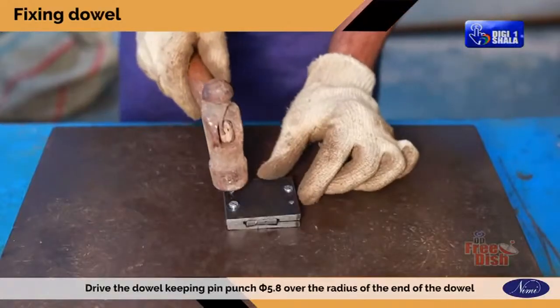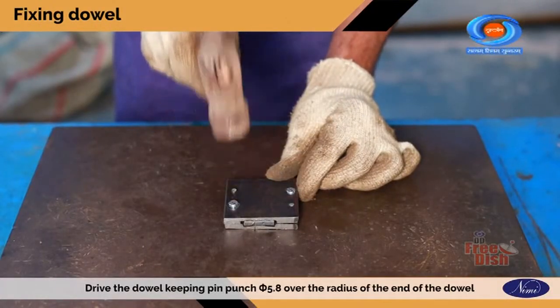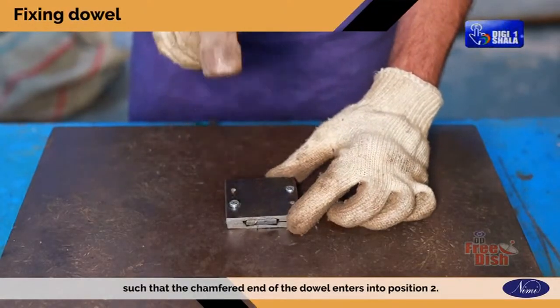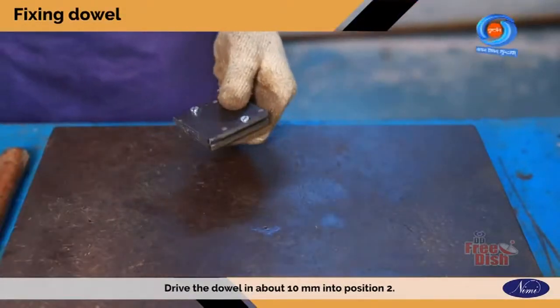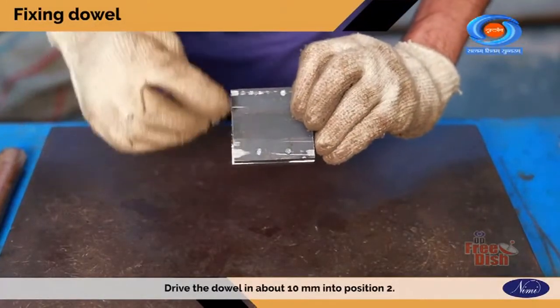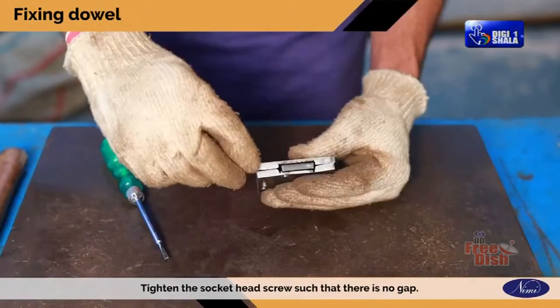Drive the dowel keeping pin punch diameter 5.8 over the radius of the end of the dowel such that the chamfered end of the dowel enters into position 2. Drive the dowel in about 10 mm into position 2. Tighten the socket head screw such that there is no gap.